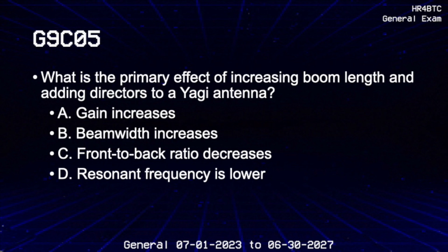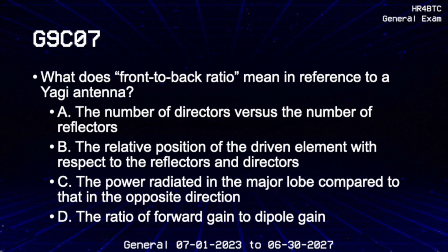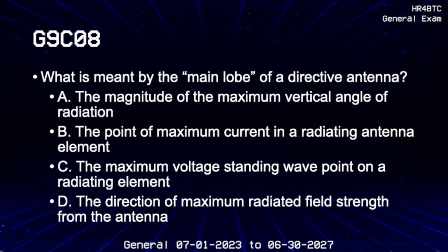What is the primary effect of increasing boom length and adding directors to a Yagi antenna? Gain increases. What does front-to-back ratio mean in reference to a Yagi antenna? The power radiated in the major lobe compared to that in the opposite direction. What is meant by the main lobe of a directive antenna? The direction of maximum radiated field strength from the antenna.